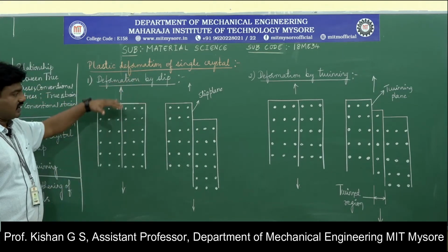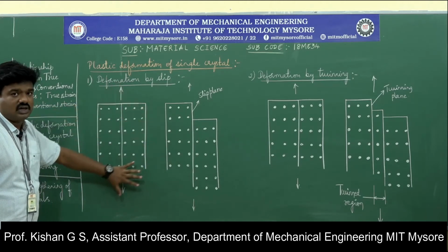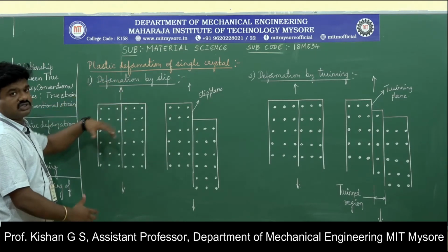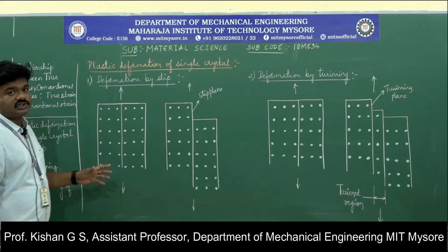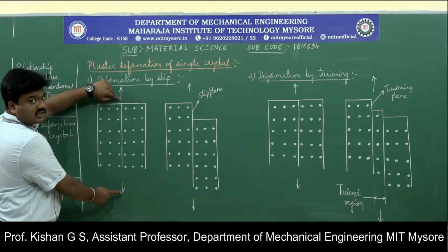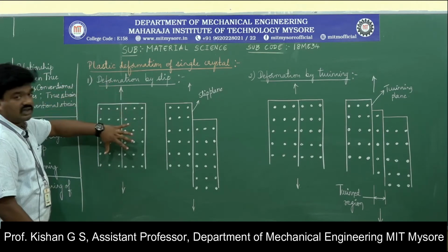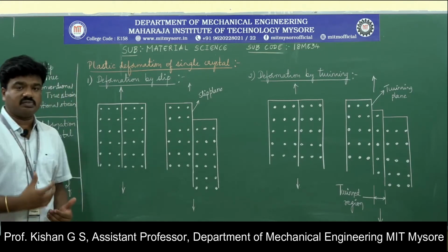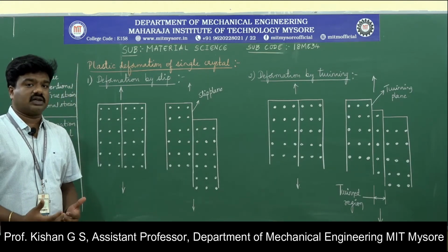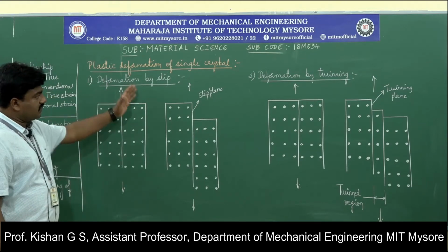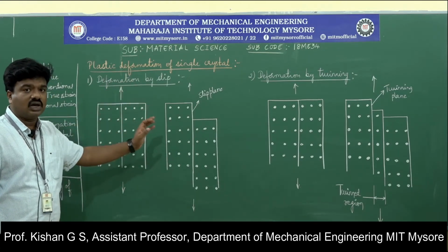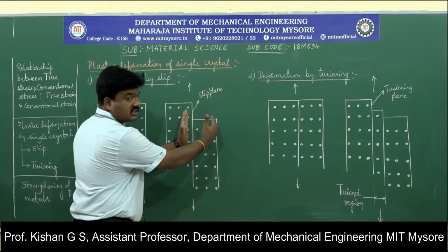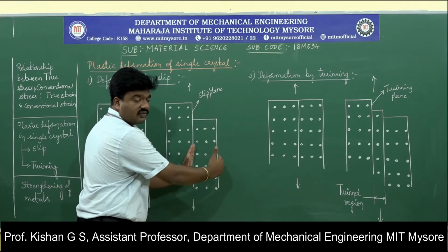Here we have taken the consideration of a crystal with an ideal arrangement of atoms. Once the material is subjected to a particular load, say for example the application of tensile load, these two arrow marks represent the outside pull on the material that results in the tensile condition. Once a dislocation is identified in the material when it is loaded in the plastic limit, deformation by slip occurs when a group of atoms get dislodged from its atomic site and form another set of arrangement.